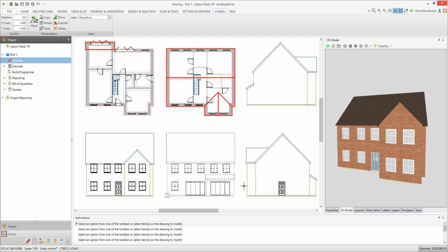There may be various other things that you want to change about an elevation. For example, there may be lines you want to lengthen or shorten, or features you want to remove. As you can see, at the moment the elevation is one symbol. You can explode the elevation symbol into its constituent lines and symbols, ready to make changes. However, please note that once the elevation has been exploded, it cannot be updated using the Recalculate elevation tool. Ensure you're happy with your plans before you explode an elevation.